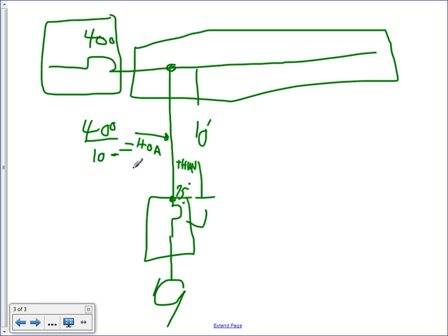Can anybody? So 40 amp under 75, is it number 8 or number 6? I can't remember. Number 8? Okay. So number 10 cannot cut it at that value. So the smallest conductor that you can tap is number 8.